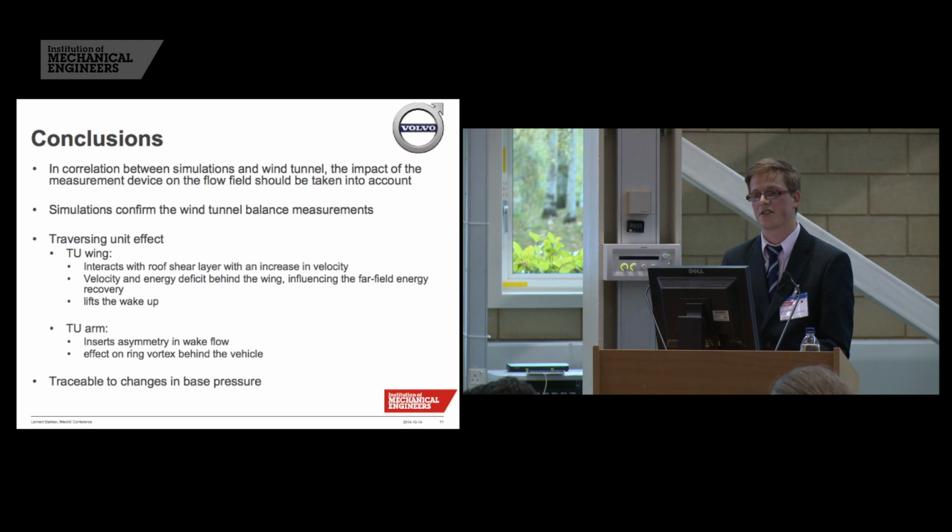We can't just ignore it and just compare CFD directly with the wind tunnel results, because if we have a device, and definitely if the device is intrusive, as with the pressure probes and traversing arm, then we have to take that into account.